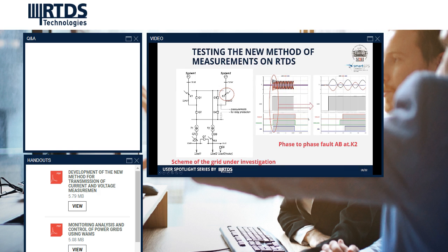To sum up, the result of the comparison of the PAC action time and the transmission of the trip commands shows that the new method for measurement transmission ensures the required speed of the distance protection